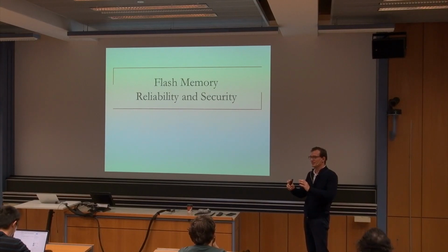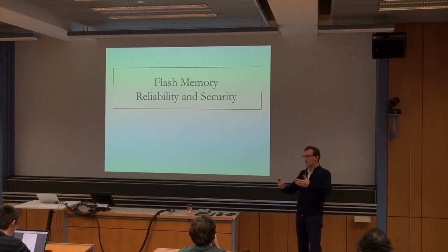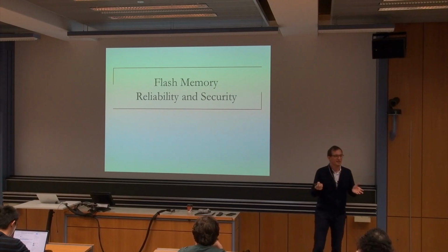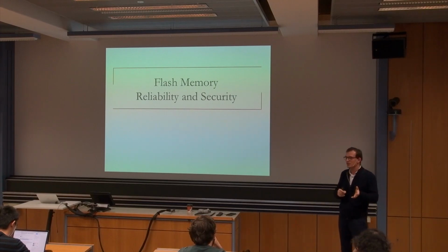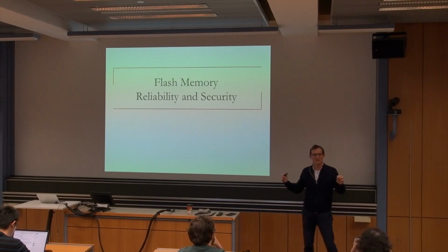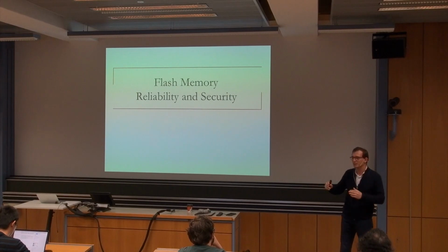As we've seen. What do you do? Because let's assume that you have read this page and that you modified the contents of that page. Now you need to reprogram it. Reprogramming it is not easy because you cannot just write to that page, because when you want to actually reprogram, you only can increase the voltages. If you want to decrease the voltage, you need to erase it. But there is no mechanism to erase a single page. Erases are done only at the block granularity.